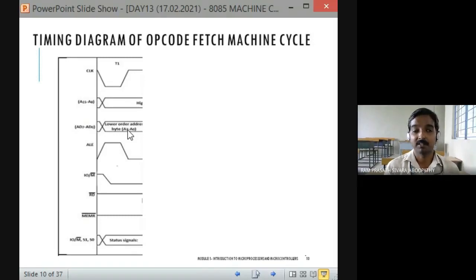What it means is that the address and data information are time multiplexed inside the processor. Fine. To demultiplex it externally, we use a latch with the enable signal from ALE. That's all. Shivakumar, can you answer now why it is time multiplexed?